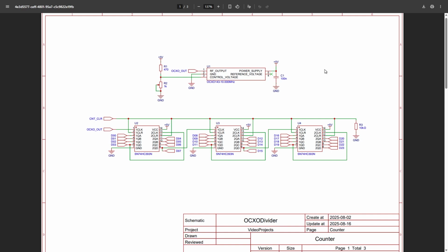We can see that I've connected all QD outputs to the clock input of the counter to its right. In effect, I have daisy chained 6 4-bit counters, giving me a counter of 24 bits. Remember, we needed 23 bits to write the number 5 million, so we could convert the 10 MHz into a 1 Hz signal.